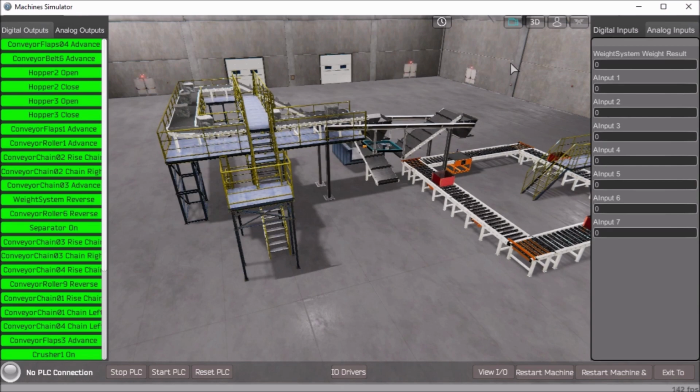So a flowchart or sequence table is used to fully understand the process that needs to be controlled. It must answer questions like, what happens when electrical power or pneumatic air is lost? What happens when input and output devices fail? Do we need redundancy? Now this step is where you're going to spend most of your time. Understanding everything about the operation will save you time. It will help prevent you from continuously rewriting your PLC logic program.